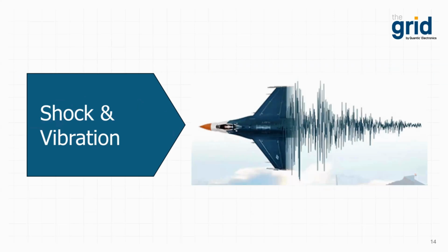Now, avionics systems are exposed to vibration, particularly in the case of rotary wing aircraft such as helicopters. Today's modern airborne weapons, such as missiles, contain their own avionics subsystems, which must be able to withstand aggressive shock conditions. MIL Standard 202 defines a wide variety of shock and vibration conditions that an electronic component must meet. It's important to ask the capacitor supplier which MIL standards that particular capacitor adheres to.